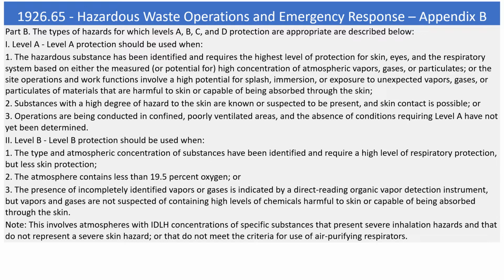2. Level B. Level B protection should be used when 1. The type and atmospheric concentration of substances have been identified and require a high level of respiratory protection, but less skin protection. 2. The atmosphere contains less than 19.5% oxygen.